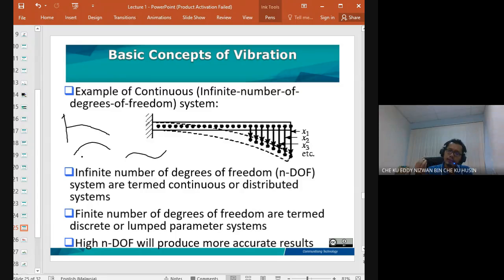When you excite at 10 Hz, there is a resonance phenomenon, because the excitation from the motor coincides with the natural frequency of 10 Hz. So what happens to this beam? It will have a deflection in the pattern of this mode.